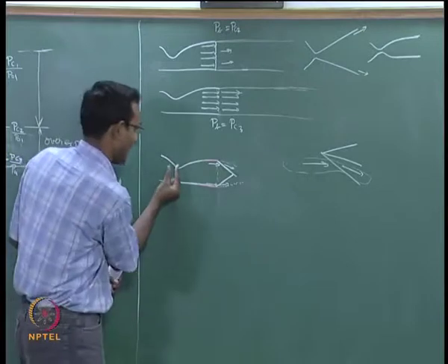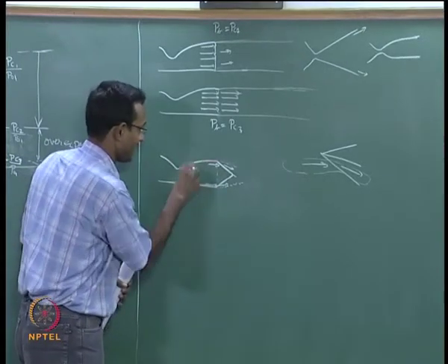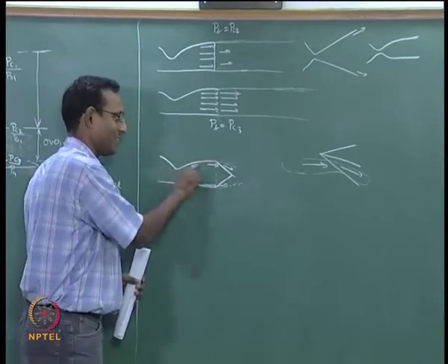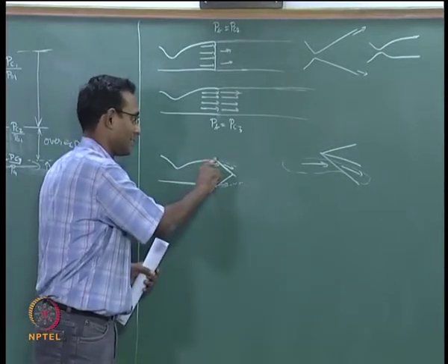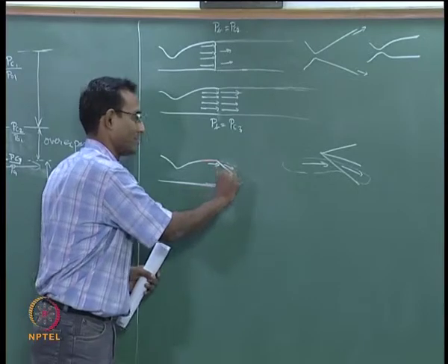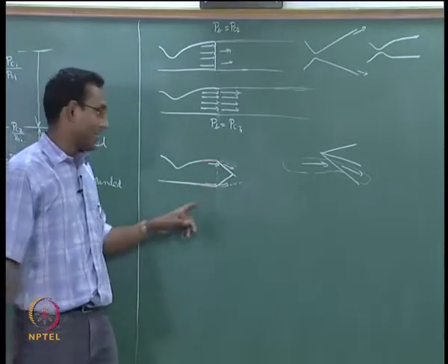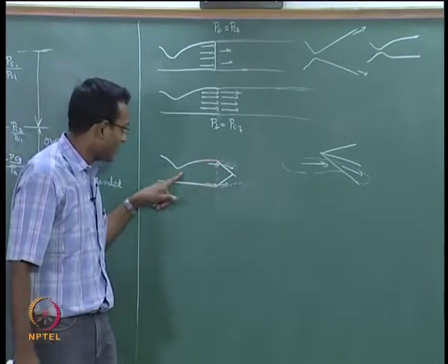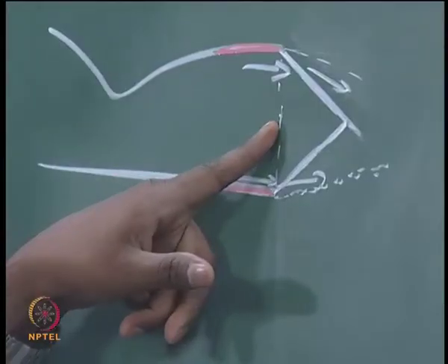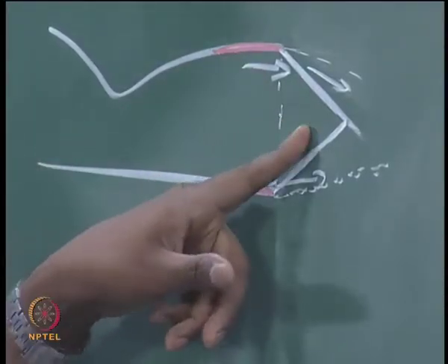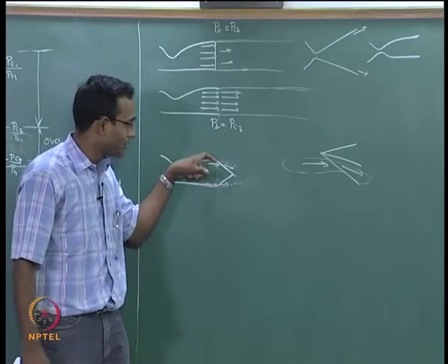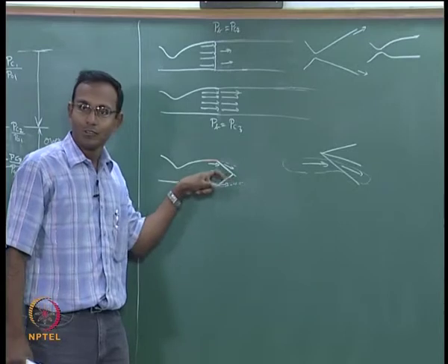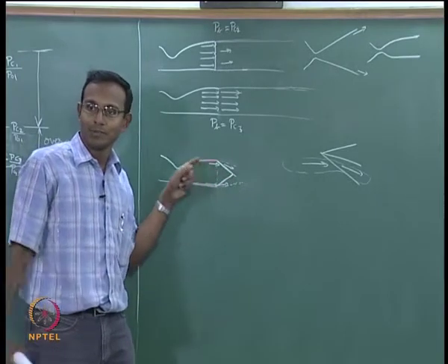I am thinking about one slab of fluid going like this, it is increasing in size as it goes here. Why does it increase here? It is expanding, it is increasing in Mach number, and when it goes here it is suddenly having to change in size. All this time we talked about one Mach number at each location axially. After exit I cannot talk about that. Why? Because of the 2D problem, I have introduced a 2D component here. Oblique shock cannot be a 1D problem, it is a 2D problem.